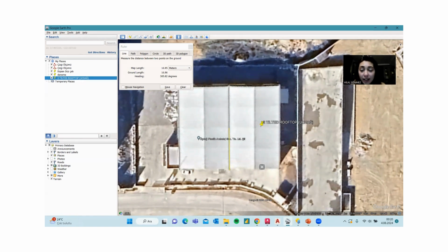In order to verify that, we can go to one ridge of one roof and calculate the heading again. The heading of the roof is approximately 306 degrees, and when we go to another ridge of the roof, it again corresponds to approximately 306 degrees.